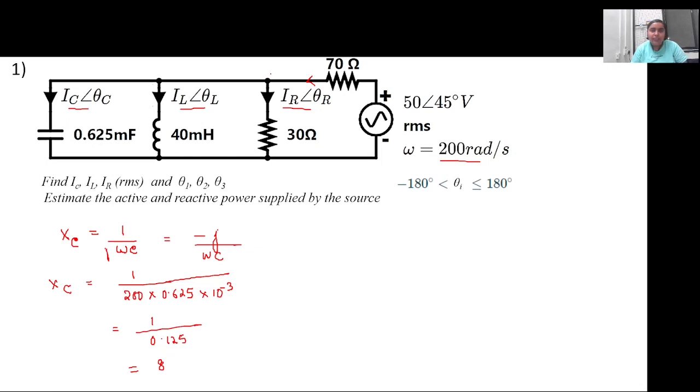To calculate this particular current, if we can get the net impedance across this branch, we can have one single loop and calculate the total current that is coming through from the source, right? Since these are connected in parallel, we will simplify the circuit. For that, we are calculating for each of the branches.